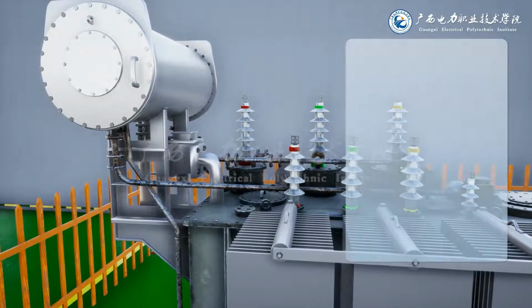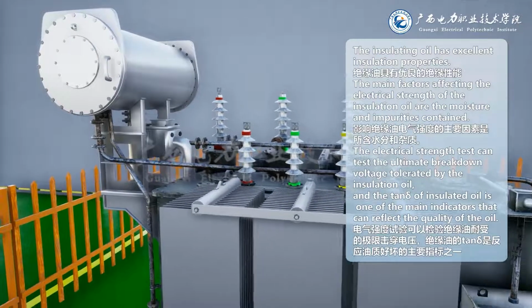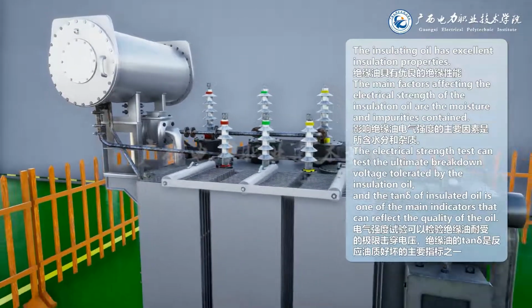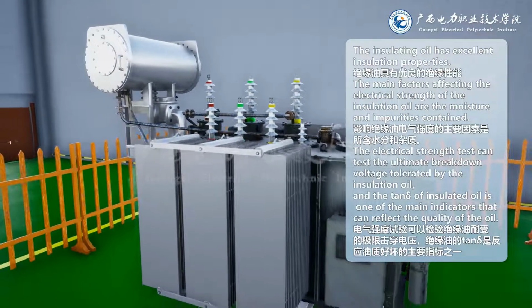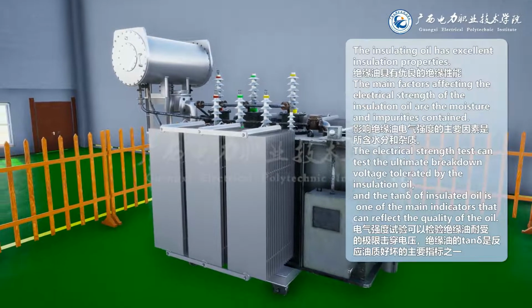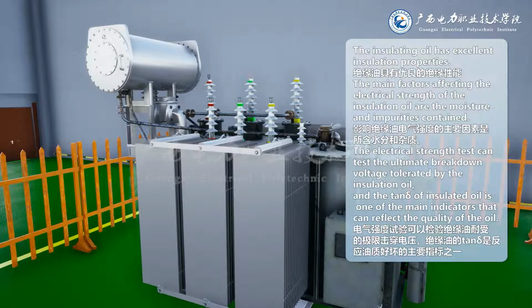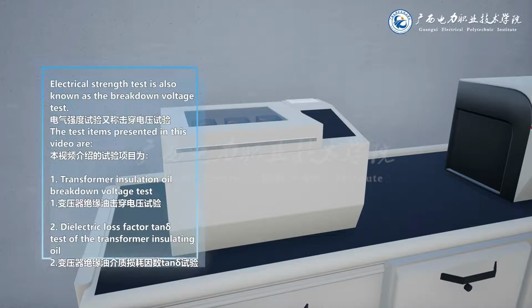The insulating oil has excellent insulation properties. The main factors affecting the electrical strength of the insulation oil are the moisture and impurities contained. The electrical strength test can test the ultimate breakdown voltage tolerated by the insulation oil, and the tan δ of insulating oil is one of the main indicators that can reflect the quality of the oil. Electrical strength test is also known as the breakdown voltage test.